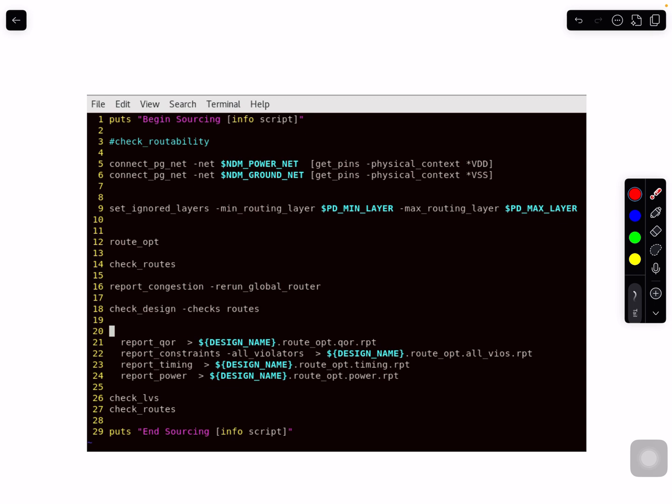You should have, at this stage, CTS, clock tree synthesis, done. As part of clock tree synthesis, you also want to make sure your clocks are routed. This routing stage is not going to route clock nets. Clock nets should already be routed in this database. So that is the other thing you want to check. Okay: legal placement, CTS done, CTS routes done. One other thing: the CTS routes need to have a don't touch on them, because you don't want to touch your clock tree during this stage. This is only for signal routing.